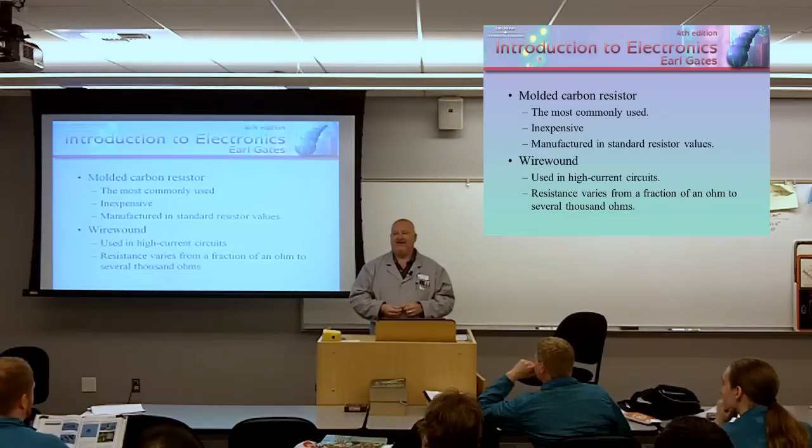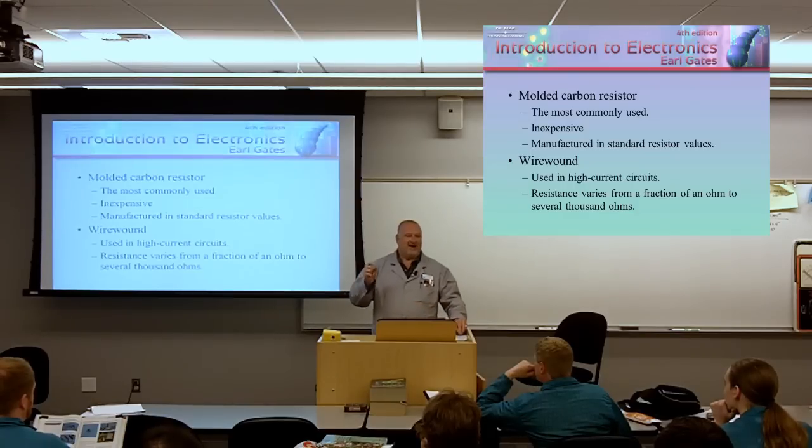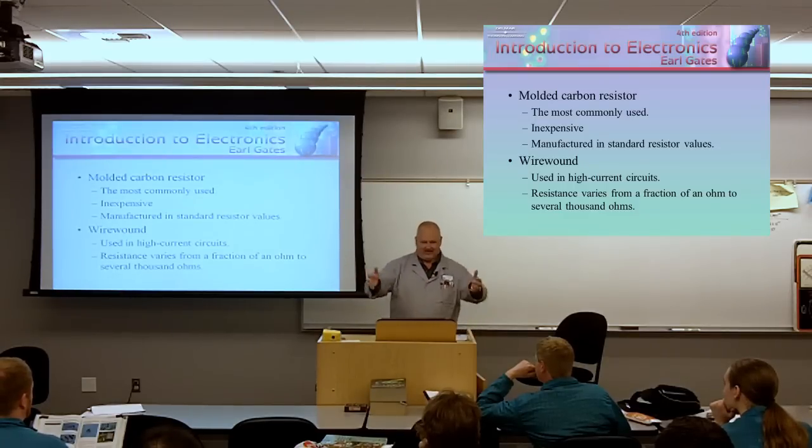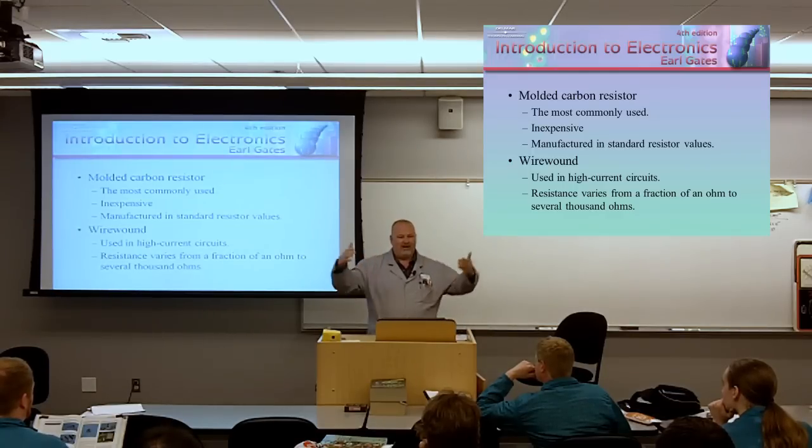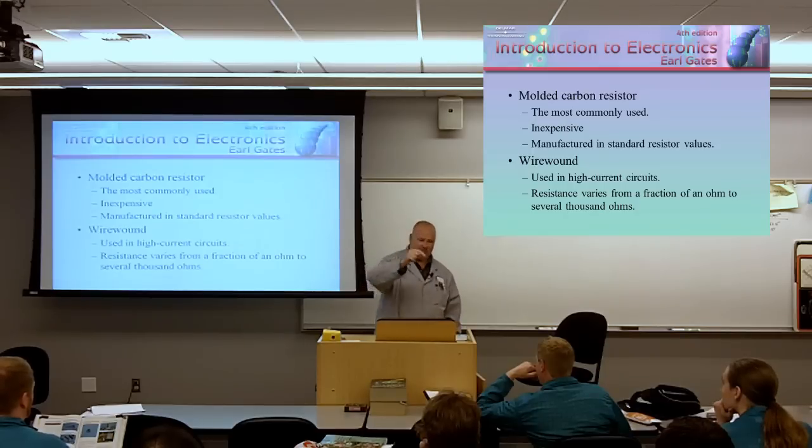One of the things they did is that the majority of boards that were rejected were because of this capacitor. They used 20% tolerance capacitors, and the circuit would not tolerate that. It had to be right in the zone. So I would go to stores and get a bin of capacitors, test every one, and sort from 20% tolerance to like 5% tolerance and keep those capacitors. When I ran into that problem, I would just unsolder that cap and put the new cap in.